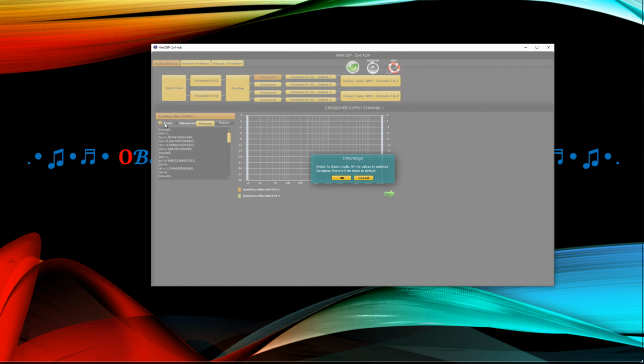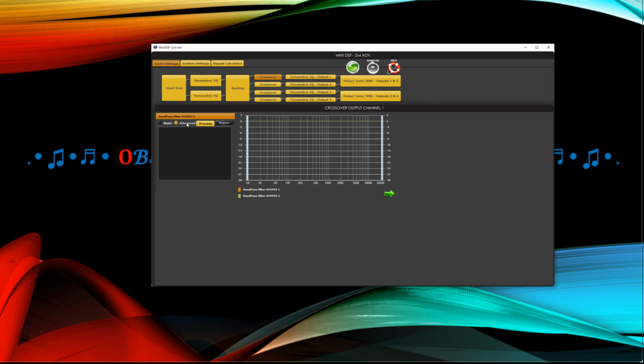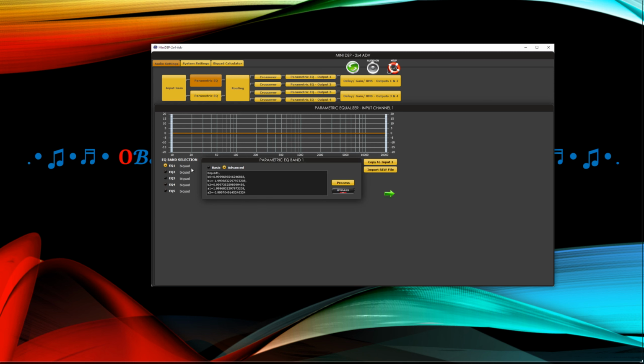It's very easy. This is the basic form, and in the advanced format, it will be empty, and you just paste what you copied from the Excel. As you see, it's here from biquad 1 to biquad 8. You have to always enter these biquads even if they are 0, so you can't just cut short. But if you're going to add this to, for example, the parametric equalizer, it accepts only 5, so it should be something like that here. Let me try. And the last one I think shouldn't be. And process.